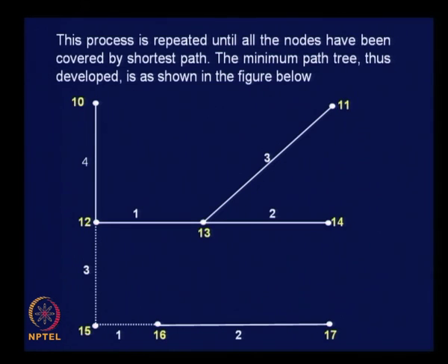You can see that a number of links have become redundant and hence removed from the minimum path tree. This is what we are looking for. When you assign traffic, you can assign using this network. The rest of the links are useless as far as this particular zone centroid is concerned, if you take the minimum path tree as the basis for traffic assignment.